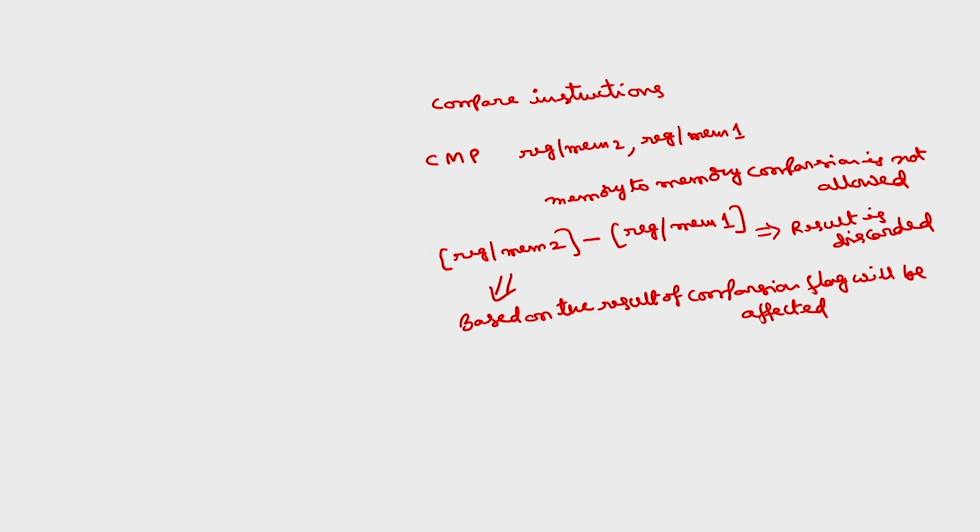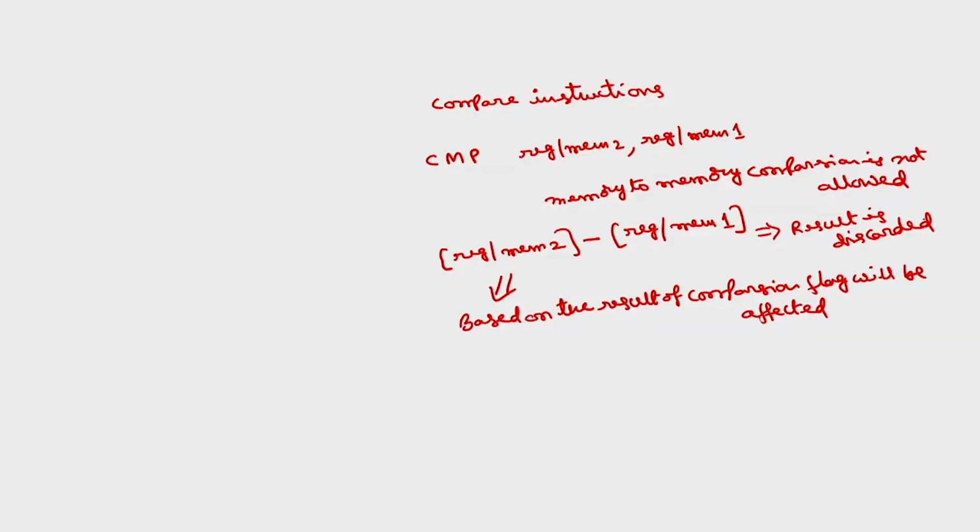If the zero flag is set after this operation, it means both the numbers are equal. So, like that we can compare which number is larger, or whether the given 2 numbers are equal or not, through this compare instruction. But in case of subtraction, the result will be stored back into the destination register or memory, whereas in case of compare, the result is simply discarded. Except for that there is no difference. Only the result is discarded here. In case of subtraction, the result is stored. And we can compare directly with immediate data also.